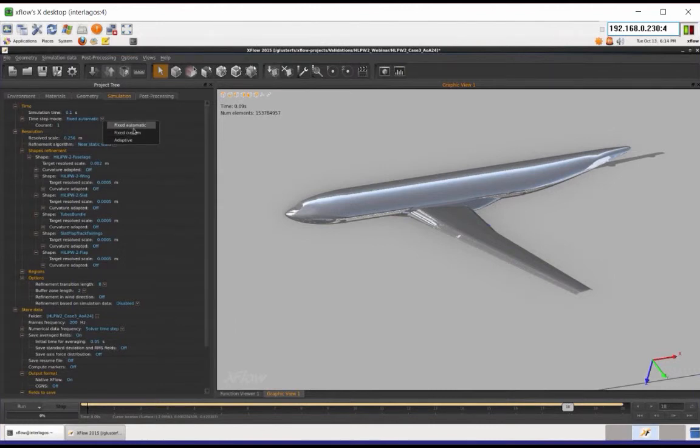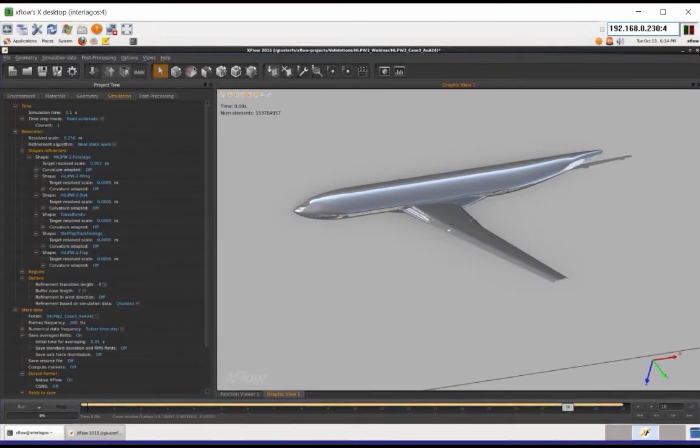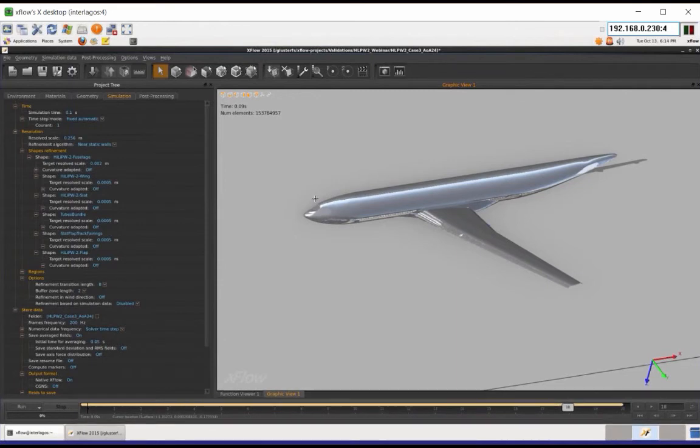In the first case, what I just said to the software is, okay, consider the boundary conditions, and please give me a time step which gives me a stable solution for that. In the second one, fixed custom, I'm actually specifying my time step. So in here, I can specify the one that I think is going to give me a stable solution, and I can input any data I would like to. So there can be something like E-5.